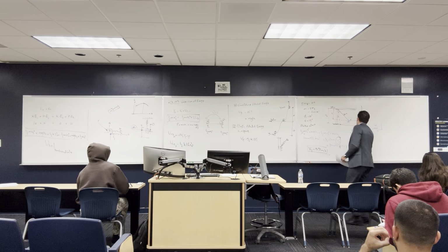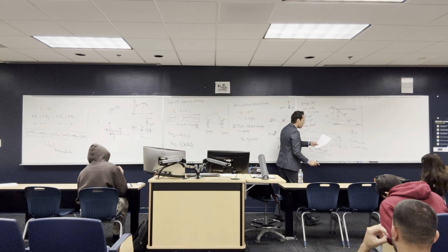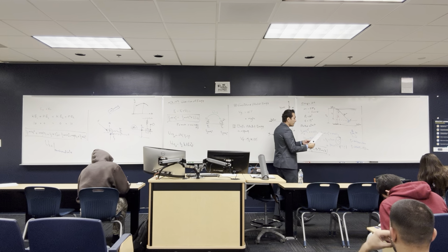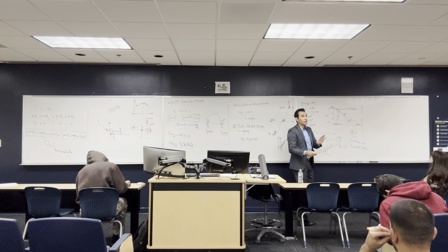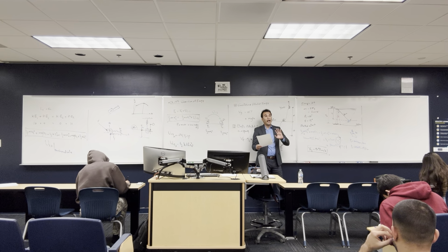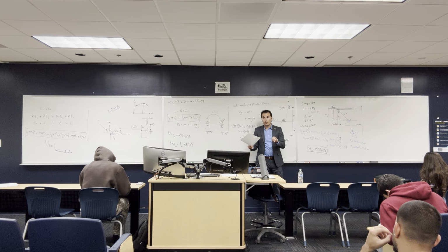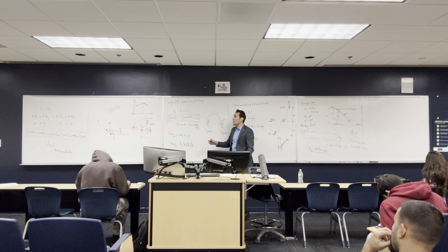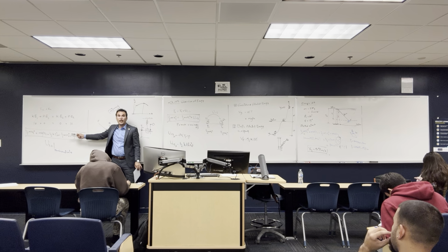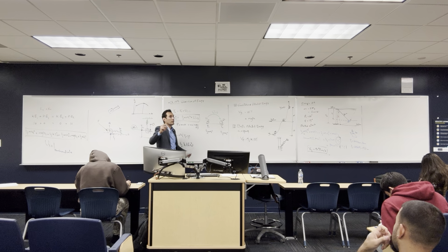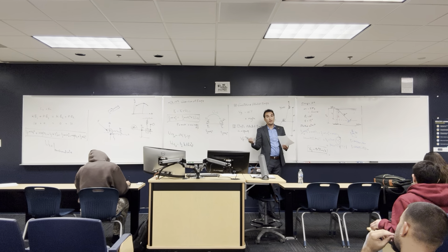That's the first part that I'm asking for in this question. The second part that I'm asking for in this question, find the tension in the cord. If I ask you to find the tension in the cord, that's forces. So this is how you know what approach you will use. If I ask about velocities, definitely the velocities are going to lead us to the conservation of energy, because that's the only rule that has the velocity. That's why we call the energy and the work methods velocity-based methods.